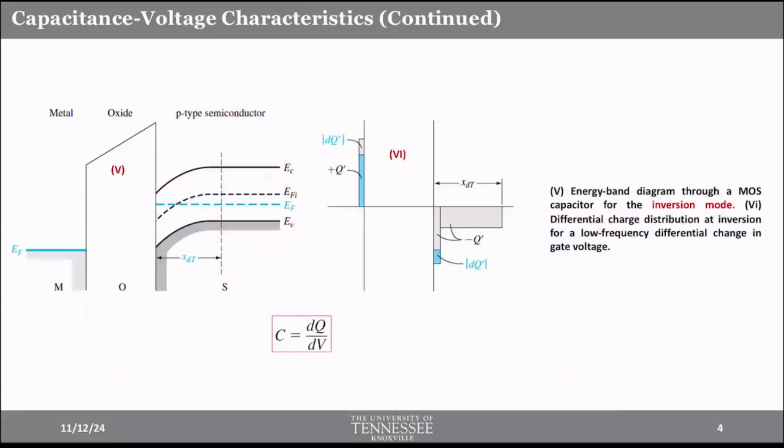So how can we actually determine the capacitance of a MOSFET? Think about it. I have just previously mentioned capacitance is not just the charge. If I tell you to measure the capacitance, capacitance is not basically the charge. Capacitance is the change of charge. So for example, you have a device, you change the voltage a little bit, you measure the charge difference a little bit. Now divide these two things.